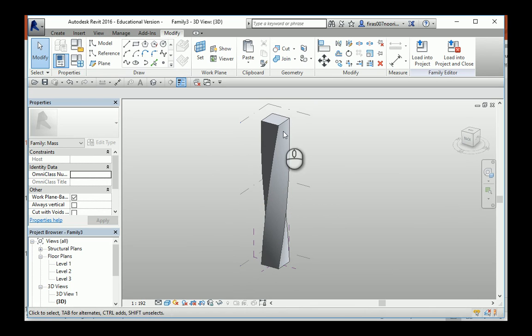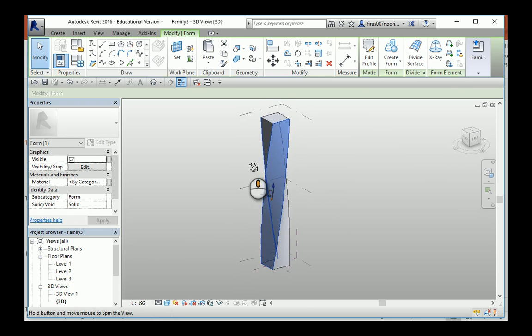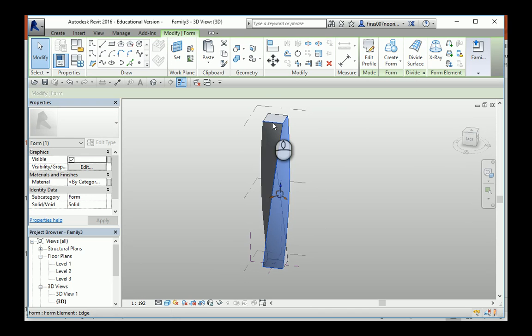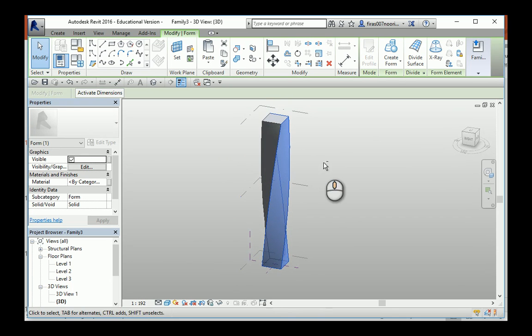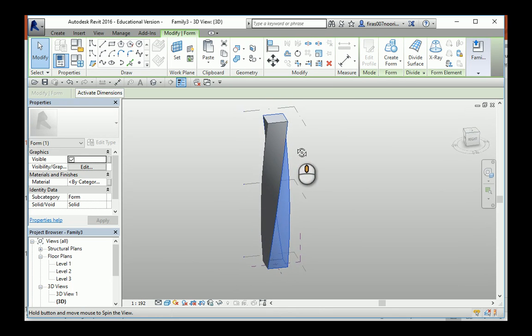That being said, now all I need is to add subdivision to that. So carefully hover above any part, let's say here, and then press tab once, twice, and click. See, now I selected the face. Again, hover, tab twice, 3 times, 4 times, 5th, and then control and then click. I'm using this method just because I'm too lazy to repeat the steps on the 4 faces that I need, so I'm going to do them once.